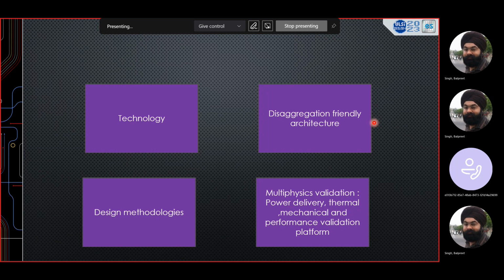Now, what we are talking about so far, I think has four parts. One is the basic technology. The basic technology is what? How do you really create these microbumps, which is the new concept? How do you really create the silicon vias, which basically go through the die, you make the connections, the punch through is basically a copper pillar, a strong copper pillar? How do you really create that technology?